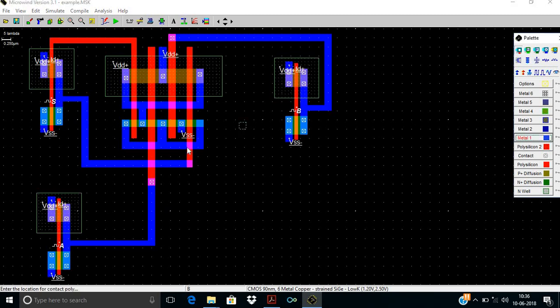Now put the contact poly to metal here. Save the design. Now everything is completed. This is the inverter. Input is S, and the output is connected to the S bar. The S is connected to here. The inverter to generate the A bar: the output of this inverter is connected to A bar. Inverter to generate the B bar. B bar is connected to this third. VDD and supply are already okay. Once again check the DRC: no violations.